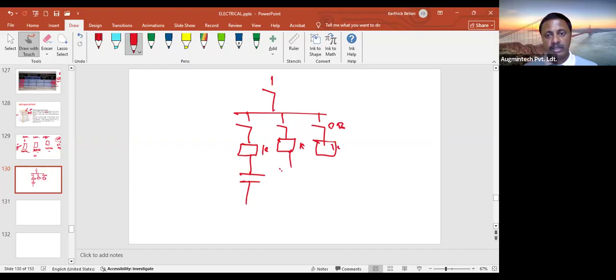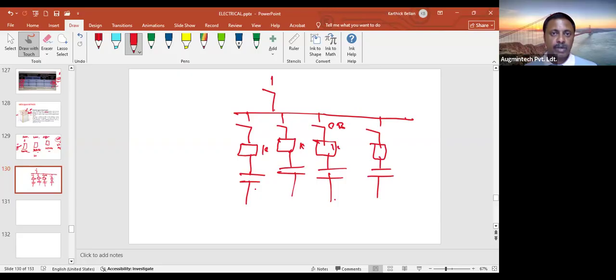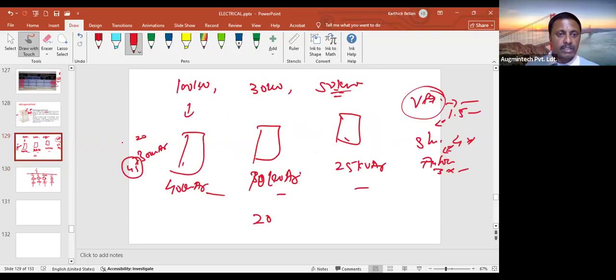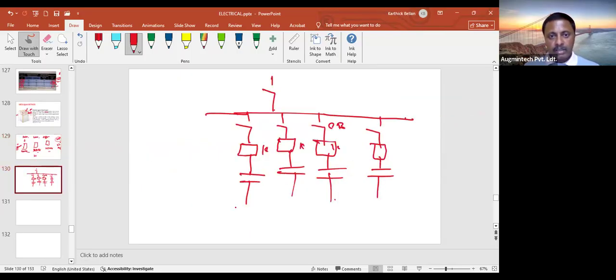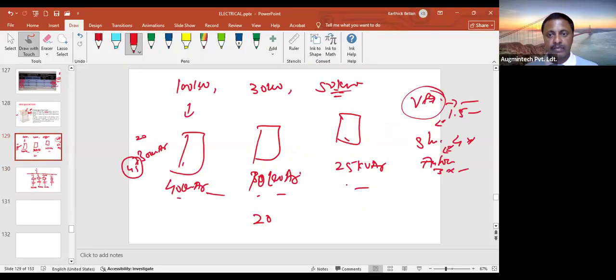These are the capacitors, right? The capacitor banks. So I have to connect it to the capacitor banks. Whenever we are designing the capacitor banks, rather than directly installing for these three motors, just consider these three capacitors. Maybe I'll install 20 kVAR, let this be 20 kVAR, 20, 40, 60. How much is our total kVAR? It's 40 plus 10, 50 plus 25, 65 it is, right?